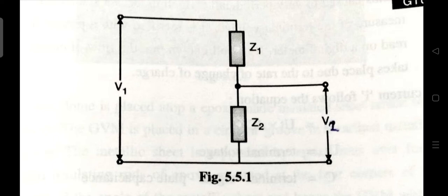So due to sudden changes in voltage caused by switching operations, flashover of test voltage, or short circuit, damage may occur to our divider elements. This is due to stray capacitance across the elements.